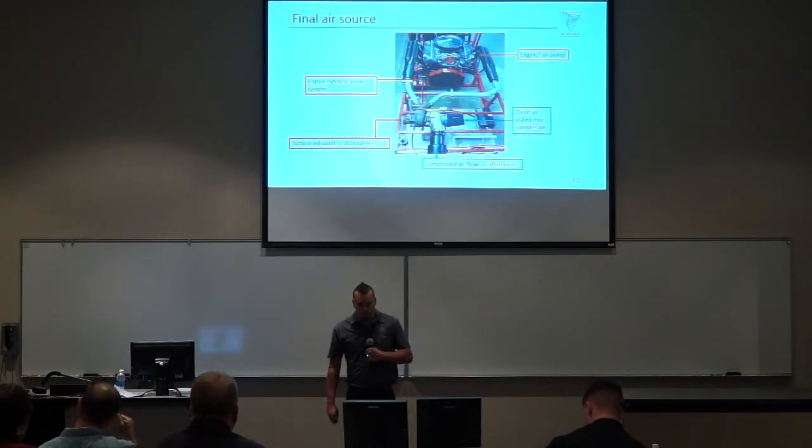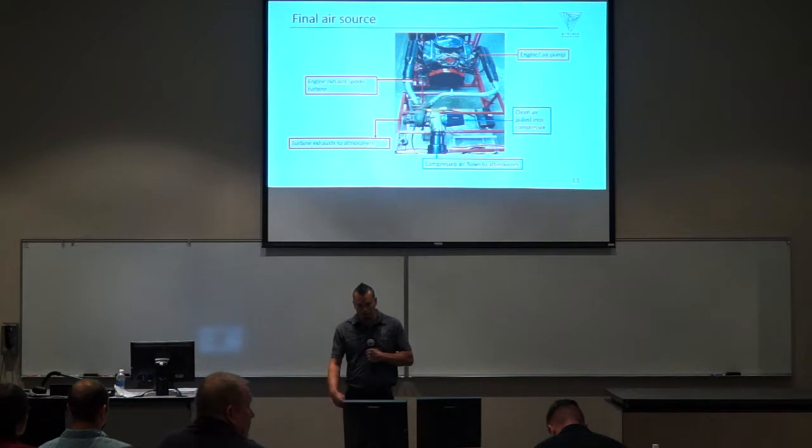So here's the air source. We have the engine, the exhaust spools up the turbo through the turbine and then exits to atmosphere. The turbine connects to the compressor with a shaft, which spools up as well and pulls clean air in and then sends that airflow down to the afterburner. Once again, in a coupled turbo, the normal way turbos work, that compressed air would go back into the engine, through the exhaust, and then through the turbine.